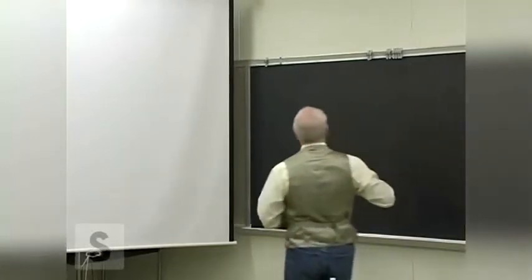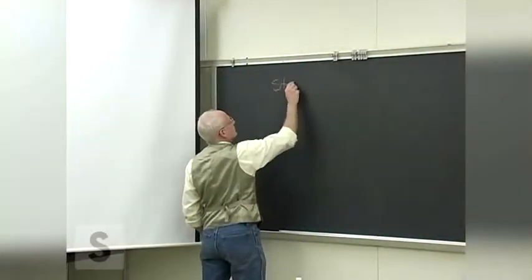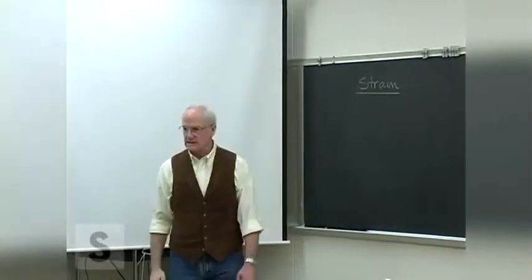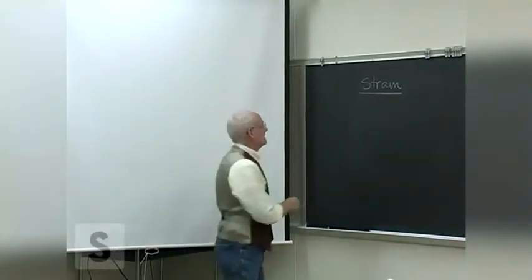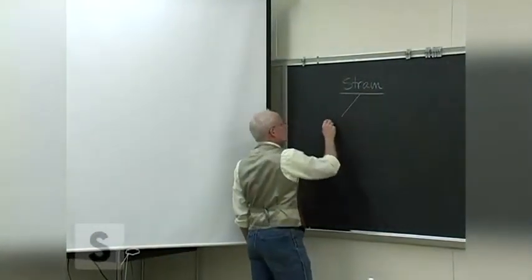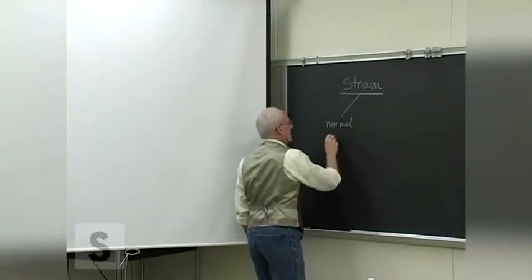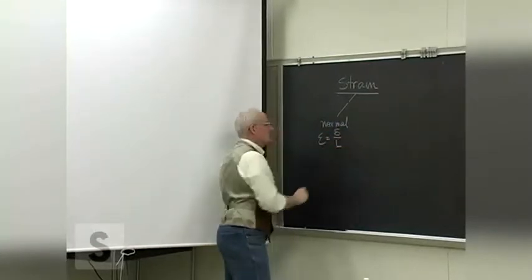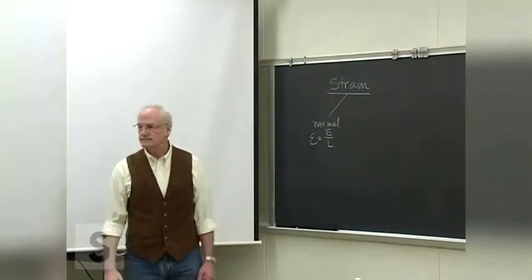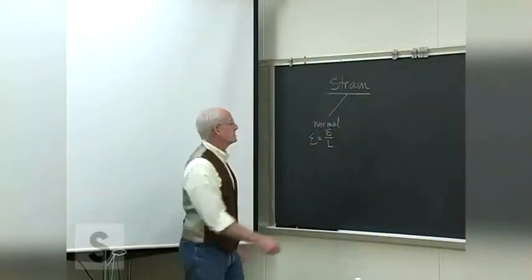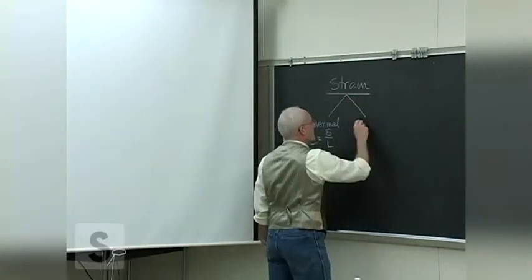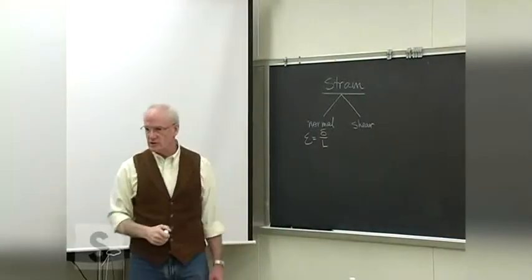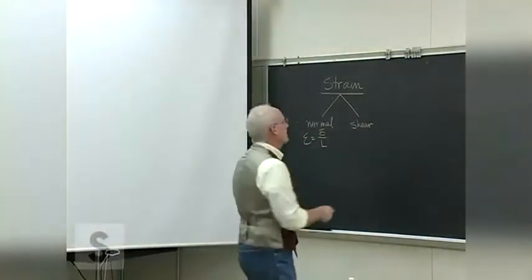All right, again, we're getting our first chance here to look at the actual response, the physical response of these materials, these elastic media, to the loads being applied to them. We just looked at the normal strain, defined as the amount it deflects under load divided by the original length. Purely a geometric problem. So we'll add to that now the shear, the response of the materials to shear, also as a physical deformation of the solid.